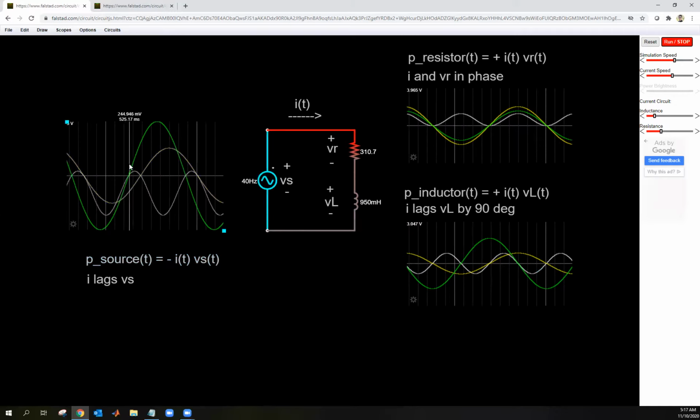Well, notice the 0 points are when either the voltage or the current are 0, good. And look at this. In this window of time, the instantaneous power is positive. Well, why is it positive? Voltage is positive, current is negative, so it's a negative number, times this negative here gets a positive number, good. Voltage is positive, current is positive, but I have a negative number, so I get negative. And over here, current is positive, voltage is negative, I have negative, but I have an extra negative, I have positive, right? And so you could just walk yourself through this little multiplication and you would see why the instantaneous power is bouncing and oscillating, right? Here it's oscillating, but not bouncing. Here it's oscillating and bouncing, okay, if that makes sense.